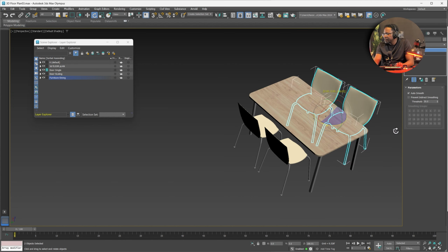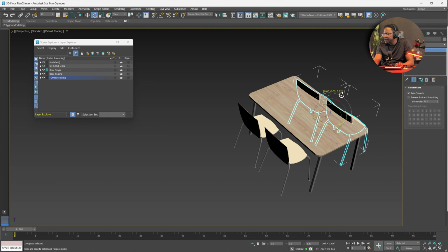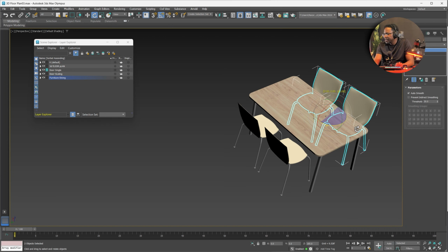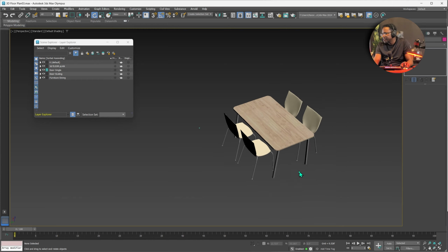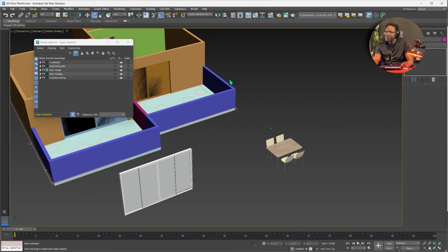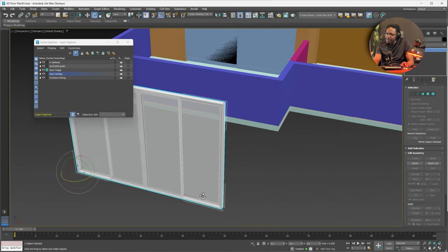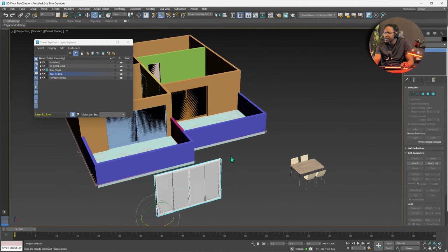And notice that it's rotating at some fine degrees here. So I'm going to undo. I'm going to turn on angle snap, which is this. So that will allow me to rotate at 5-degree increments. So 180. All right, so now this is more efficient, and so is this.